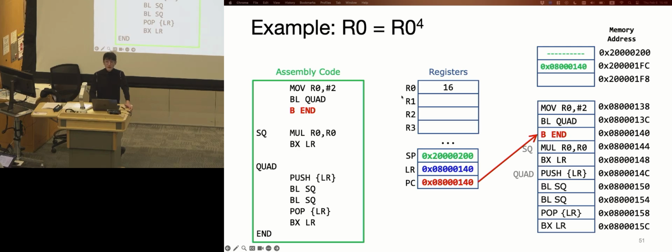What he is saying though is you just have to be careful that it's in the right stack position, because you always have to make sure it's right at the last layer. If you have multiple layers of subroutine calls, then that might cause some errors. So pop only if you pushed it somewhere before.